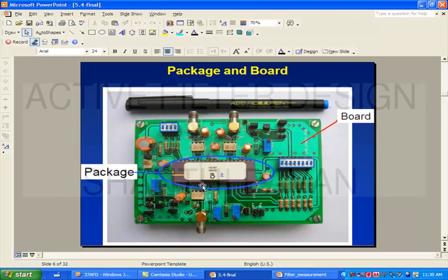So, the S parameters are measured with resistive termination, often 50 ohms, and the measurement is also much simplified with S parameters, which is why they are used all the time. So, a box which takes a 2-port and measures the S parameters. At this time you may even think of this as a box which measures Y parameters, because in principle the Y parameters can be gotten from the S parameters.